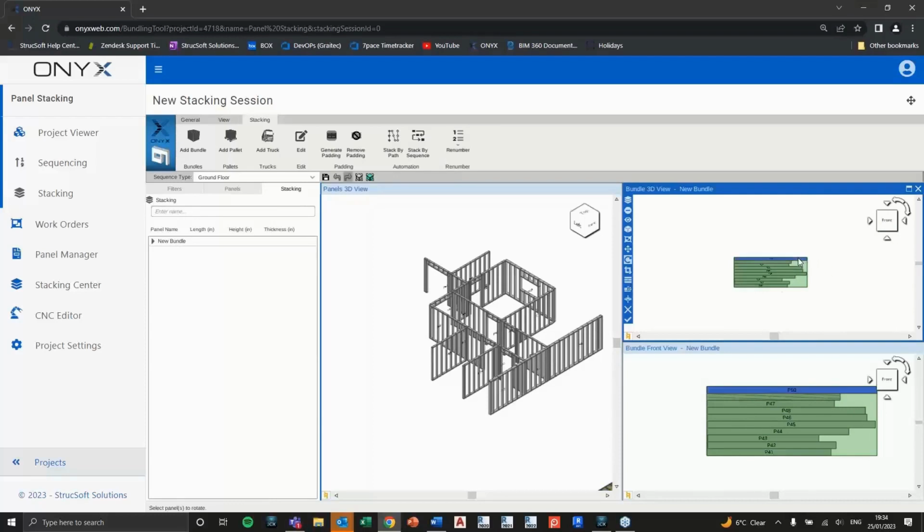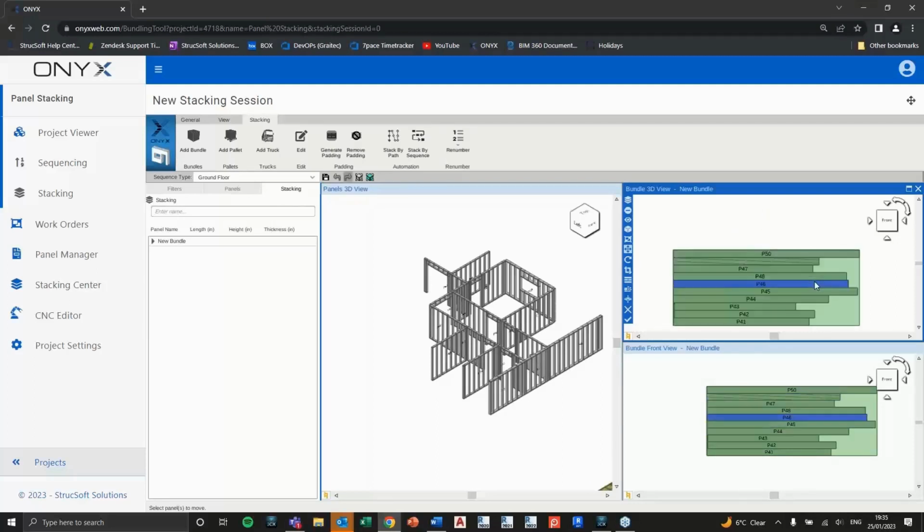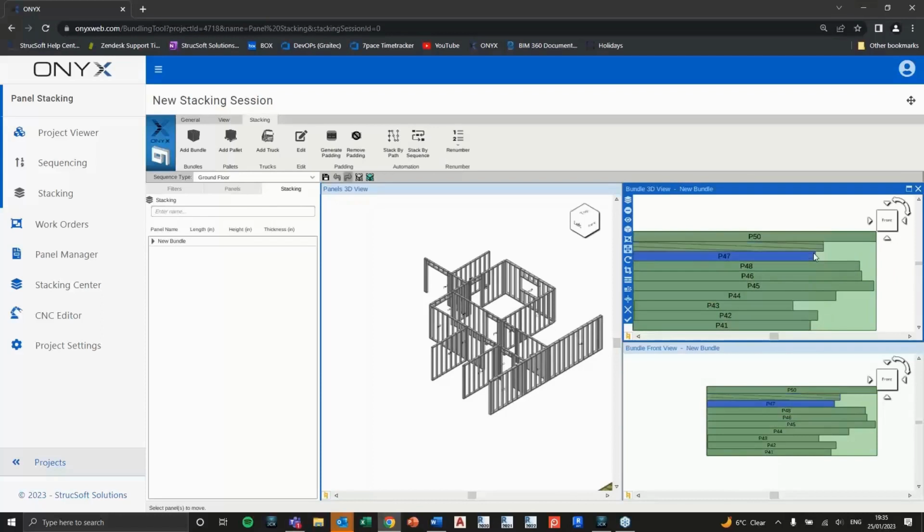Okay, so you may have some gaps in your panels, and you may want to close those gaps by collapsing the panels. The collapse option will just remove any spaces or gaps in between your panels and make sure that they're all sitting nice and flush. CL is the shortcut, but we can also hit the collapse button, and it does exactly that. Just gets rid of any gaps.